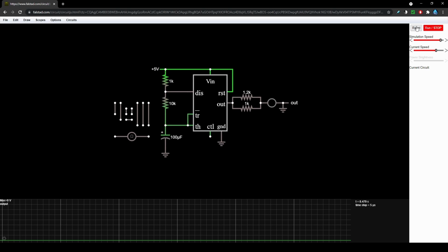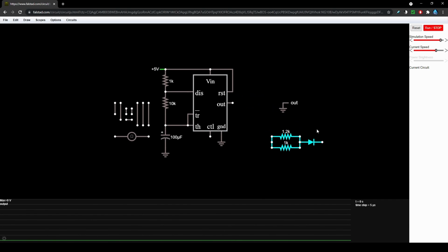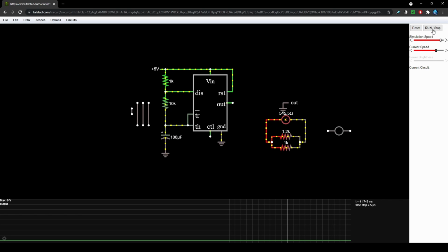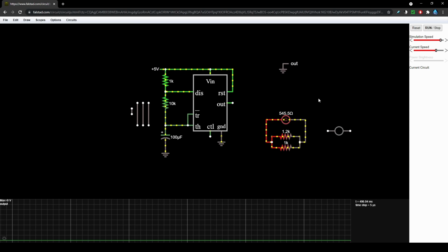So, to further prove out the resistance, you can use an ohm meter to measure the resistance. Don't forget to disconnect and isolate the components you are checking to prevent any shorts or opens from happening. As you can see, it reads out 545.5 ohms.